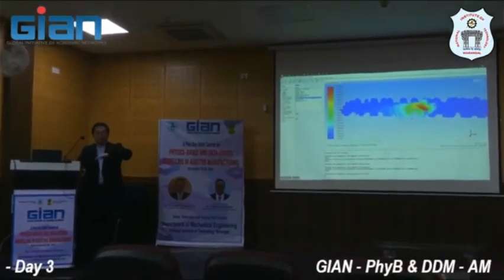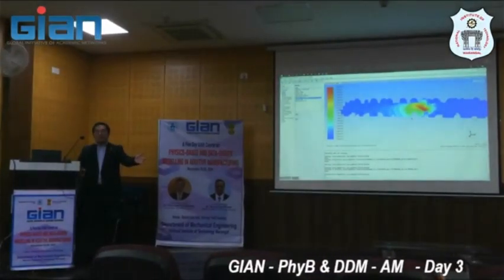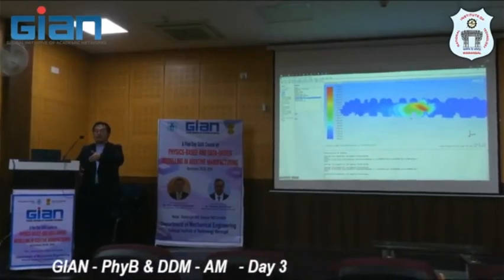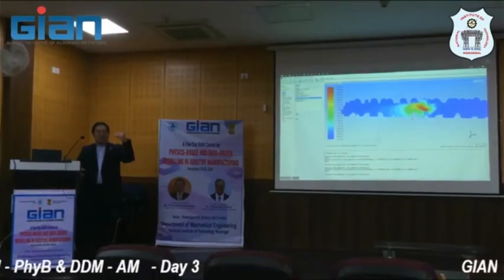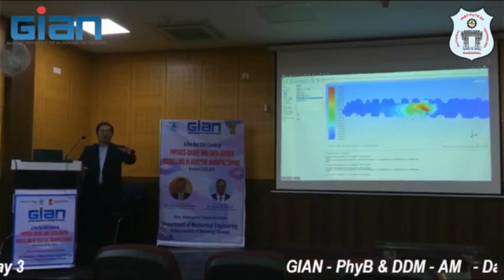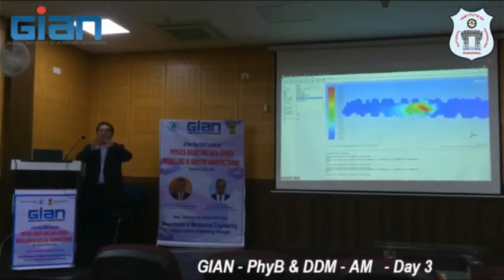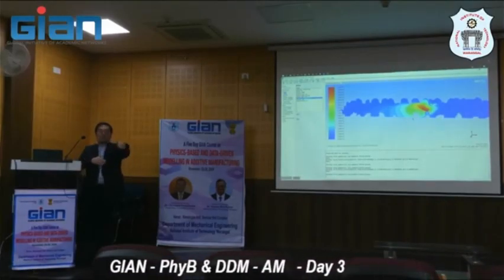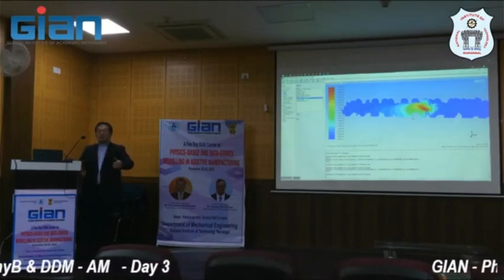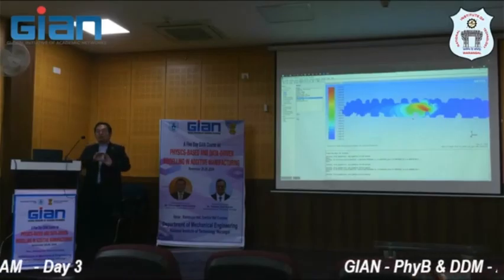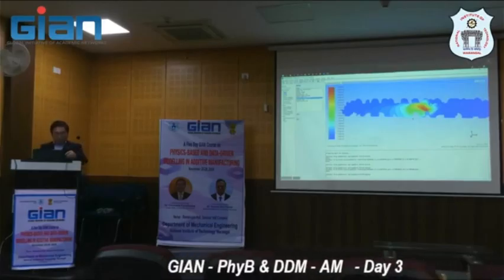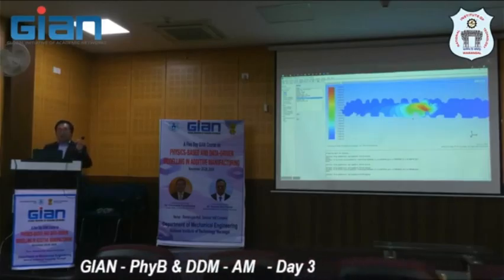But you would have another phase equation, which is alpha equal to alpha 1 plus alpha 2, where alpha 1 is the gas or metallic phase and so on, and then the equation is for alpha. It will split into alpha 1, alpha 2, alpha 3, alpha 4, whatsoever. It's the number of phases you're looking at, but you use a single equation to describe. Is that correct? Yes, this is called volume of fluid.